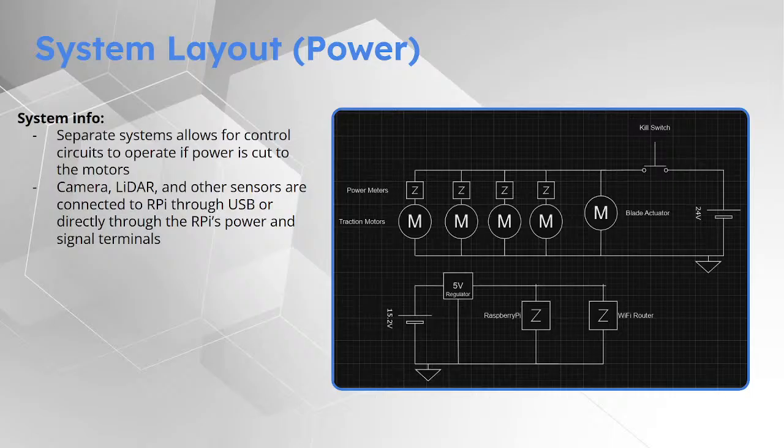ground loops. Okay. You can also break that. Part of the reason why you use isolation, optical isolation, is you're breaking the loop. That's all that really does. The whole point of that is to break the ground supply loop. Okay.